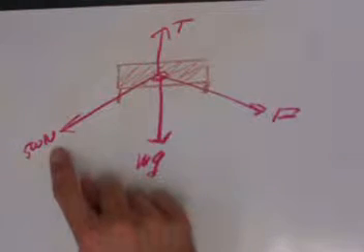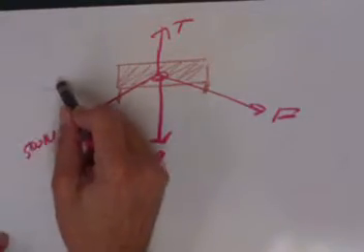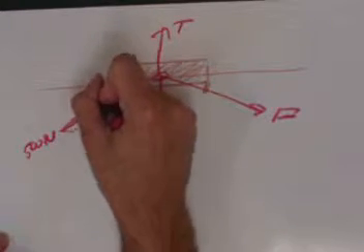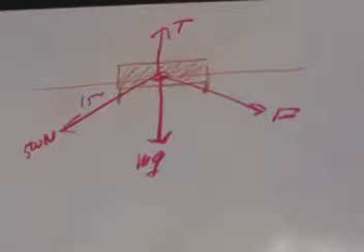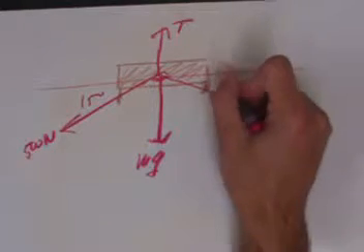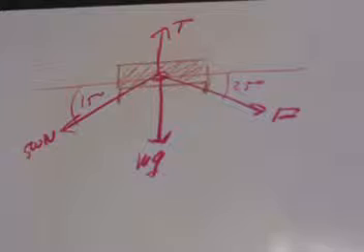There is another person holding a rope that's pulling this way with a 500 Newton force, and there's a bit of a horizontal in here you can use for orientation. That 500 Newton force is applied at 15 degrees below the horizontal. Another person is pulling on a rope on the right side with a force F, which is unknown, but the angular orientation of that one is known to be 25 degrees. So you have these two angles with the forces.